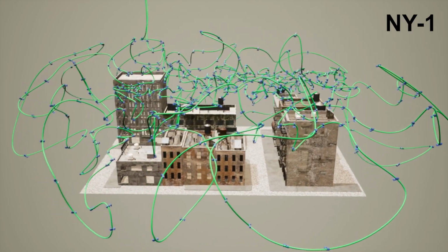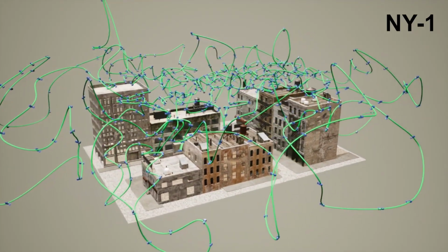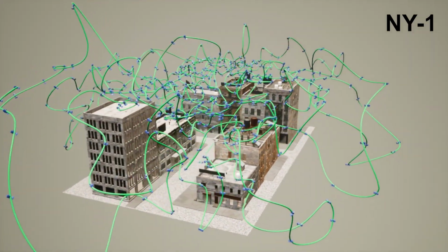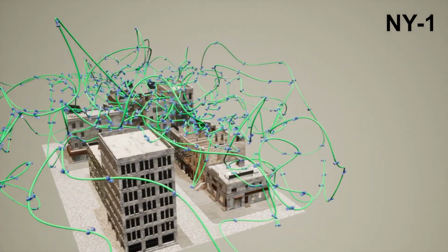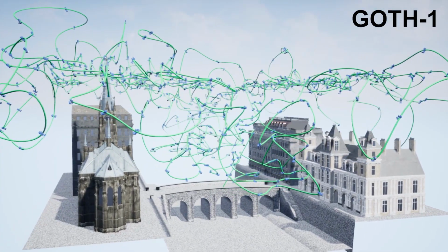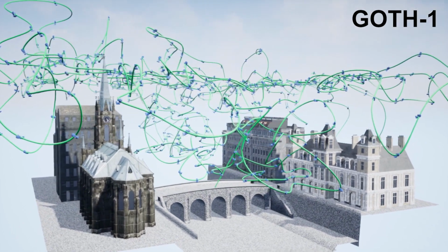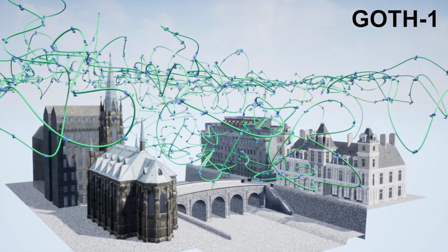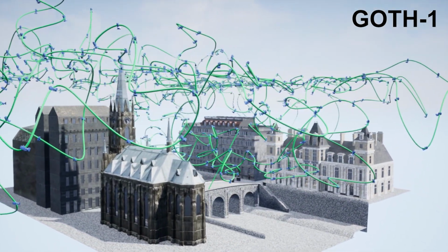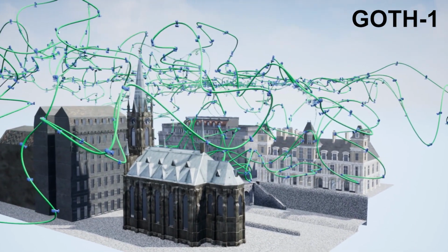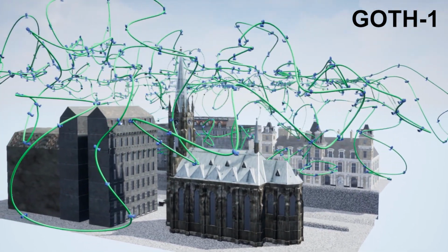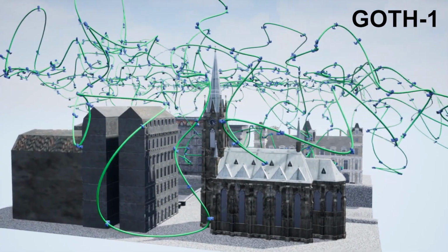We generate optimized flight paths for our 4 scenes and benchmark their reconstructability with 3 SFM pipelines, MVE, COLMAP, and Pix4D. One can see, for example, in Goth1, that cameras will drop very low to see under arches, such as under the bridge. We set our airspace limit at 2.5 meters, which allows a virtual UAV to even fly between buildings to capture hard-to-reach areas.